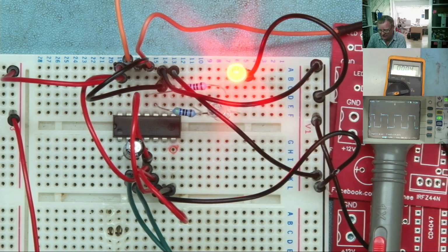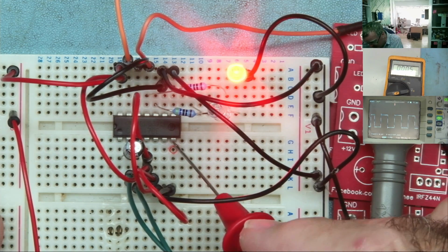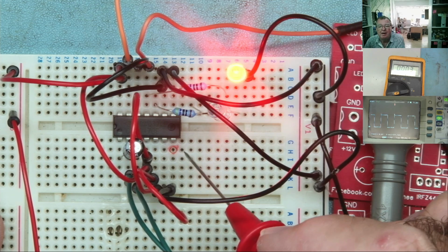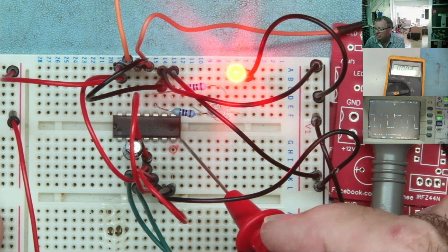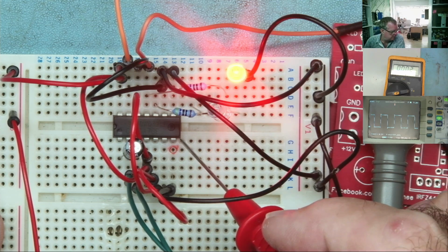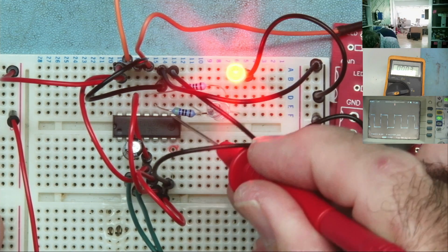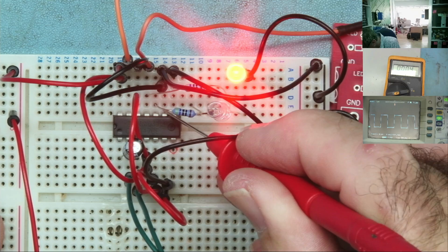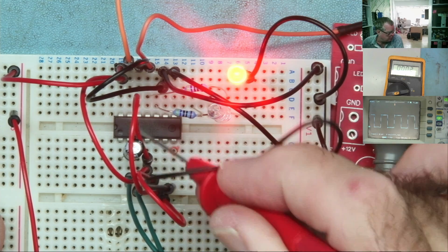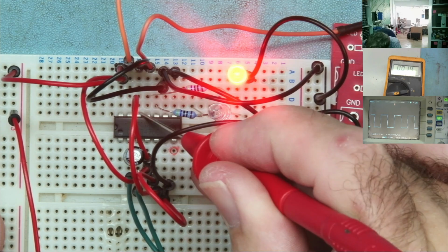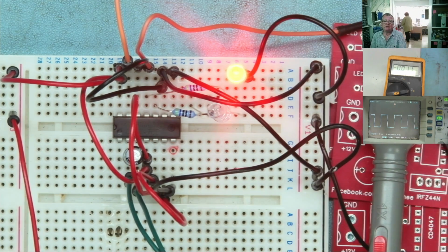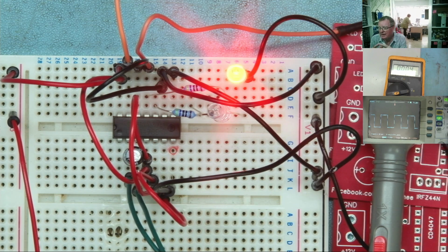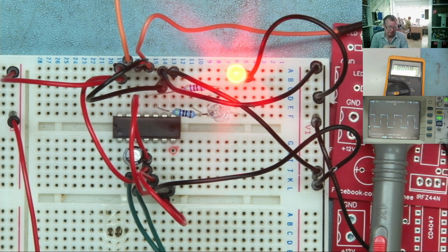So 12, 9, 8, and 7. 7, well, it's saying 0.005, so we know we have a connection to that pin. That's ground. 8 and 9. 8 has the same. 9 has the same, and then 12, which is here, has the same. So we know those are all correct. And I hope now, Max, that you can see why the truth table or the logic is correct. Then it will put it into astable mode.